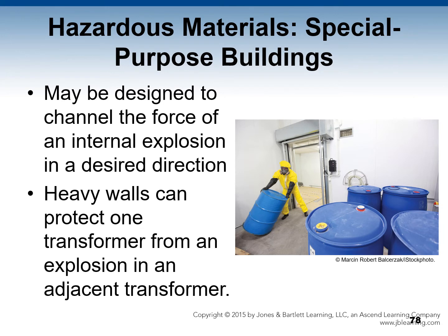Now, in regards to hazardous materials, you often have special purpose buildings. These may be designed to channel the force of an internal explosion in a desired direction. Transformer stations are often built with heavy walls to protect one transformer from an explosion in an adjacent transformer. They may also direct the blast upward or outward.